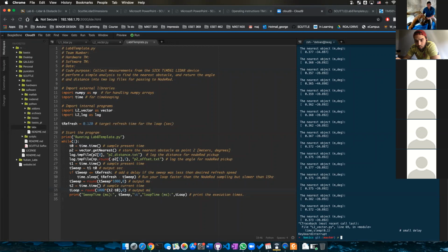The ultrasonic sensor also only returns one point. So if you want to map a room with an ultrasonic sensor, you'd either have to put a couple of ultrasonic sensors around your robot, or spin your robot around the room every time you want to take a data point.